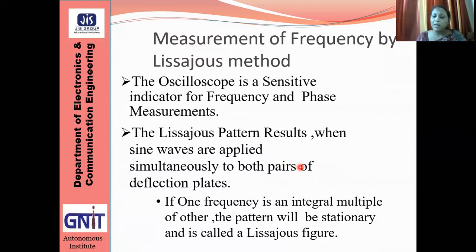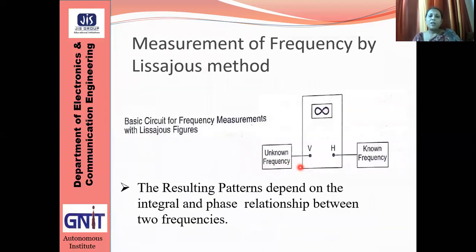So let us describe the things. This is the CRO. The unknown frequency has been applied to the vertical deflection plates and the known frequency has been applied to the horizontal deflection plates. The resulting pattern depends on the integral and phase relationship between the two frequencies.